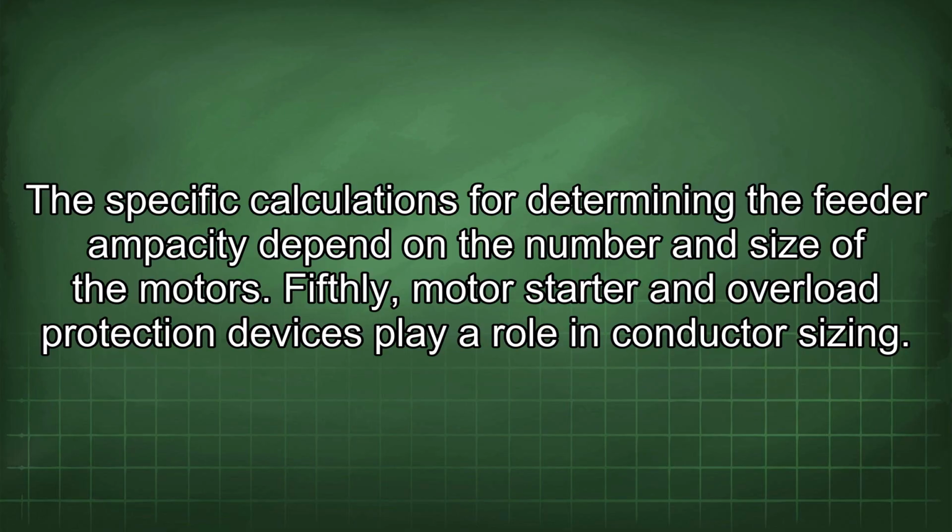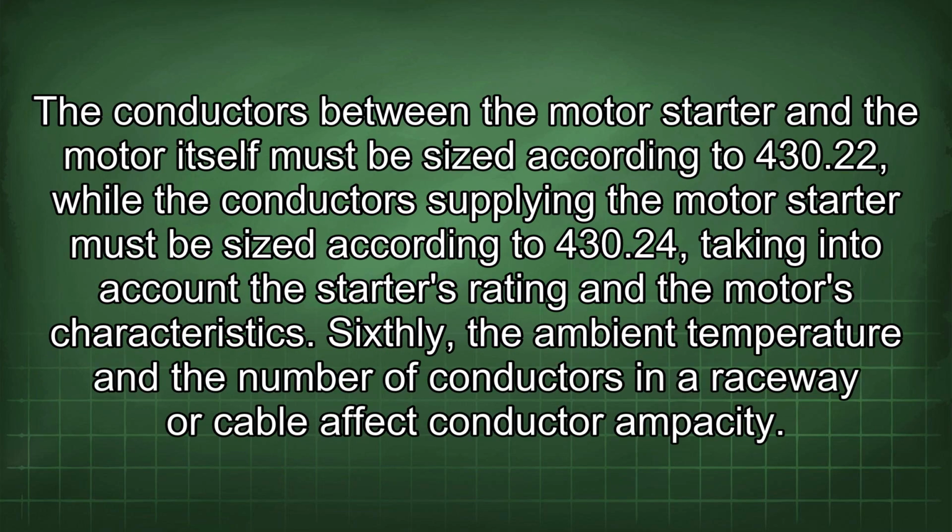Fifthly, motor starter and overload protection devices play a role in conductor sizing. The conductors between the motor starter and the motor itself must be sized according to 430.22, while the conductors supplying the motor starter must be sized according to 430.24, taking into account the starter's rating and the motor's characteristics.